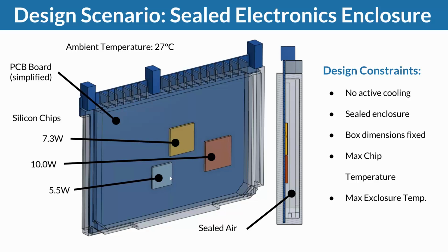So in this case, we already decreased the complexity and said, okay, we only look at the components of this PCB board that are relevant to the thermal management of this enclosure. This PCB board is put into an aluminum enclosure that we can see, a little bit translucent here. We can see the different heat loss of the 3 chips.